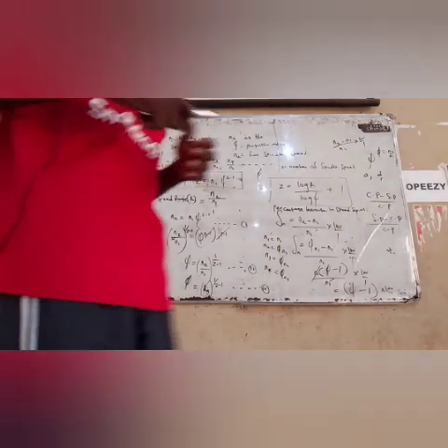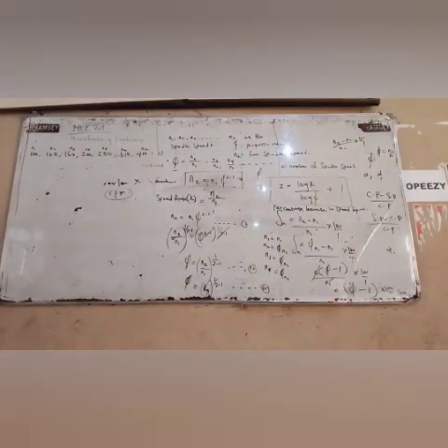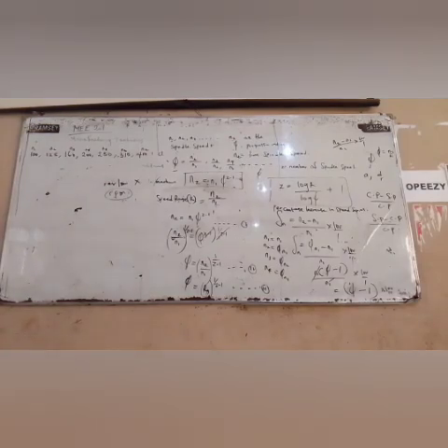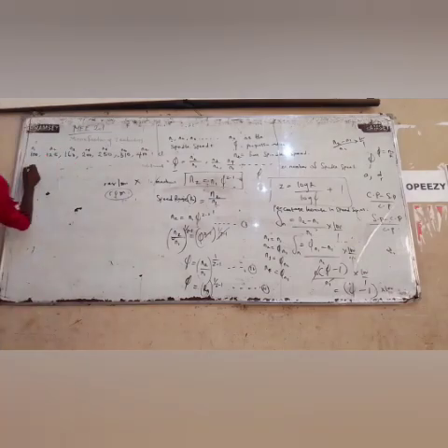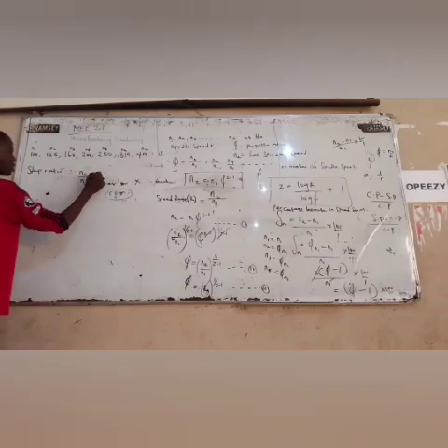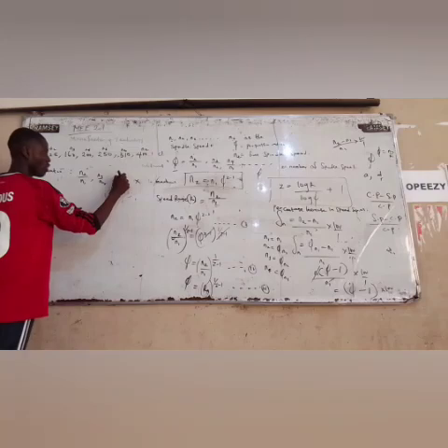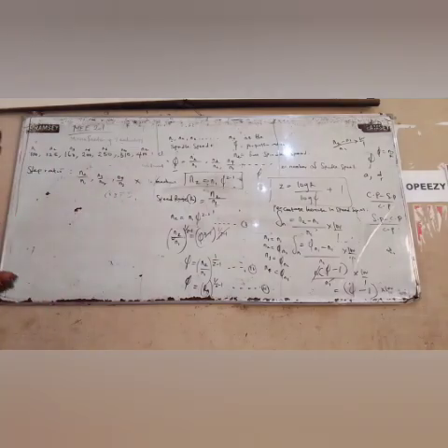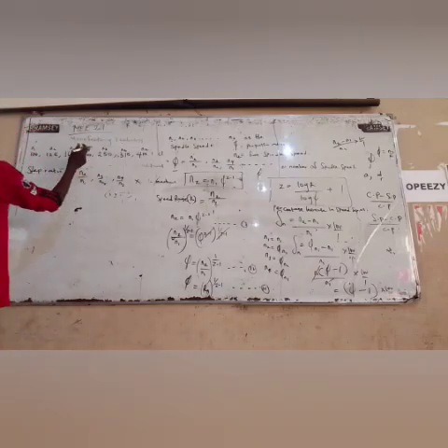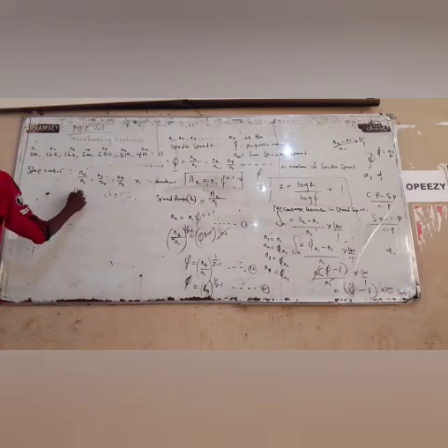Now, what's the first question? The first question is the step ratio. What is the step ratio? Step ratio is just the progression ratio. So how will you calculate the progression ratio? You just take N2 over N1, or N3 over N2, or N4 over N3. Pick any one you want to get your answer. So which one should we pick? Let me just pick 160 over 125.